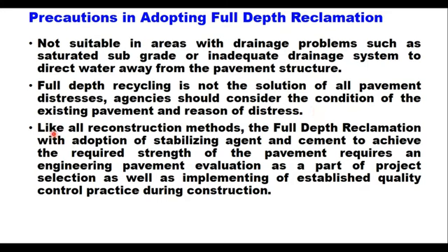And like all reconstruction methods, the FDR with adoption of stabilizing agent and cement to achieve the required strength of pavement requires an engineering pavement evaluation as a part of project selection as well as implementation of established quality control practice during construction.